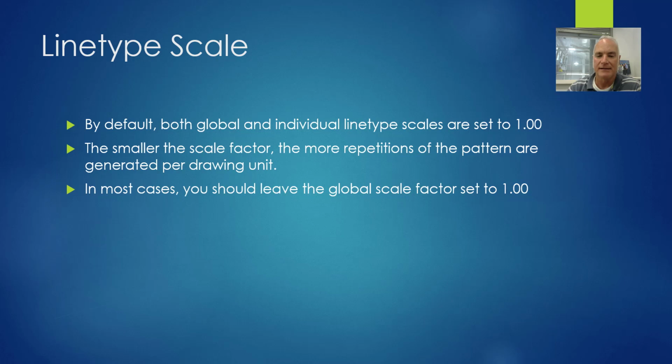The smaller the scale factor, the more repetitions of the pattern are generated per drawing unit, and in most cases, like I said, you'll want to leave that global scale factor set to 1.